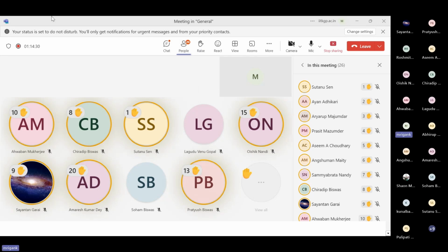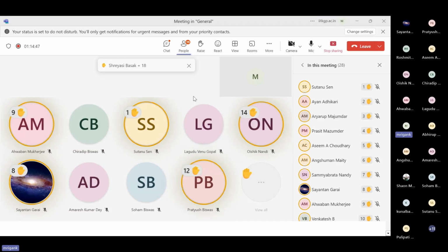So the noise chapter, the lectures on the noise analysis, is important. You should go through that, and the sizing eventually. Right now, in LT5, the problem is that the noise model we have seen is not very correct. It doesn't work properly. That's why I did not emphasize noise, because unless you can simulate it and make use of it, what is the point? When we go to Cadence, there the noise analysis will be accurate, and there we can do the sizing for mitigating noise. But conceptually, in those lectures that were recommended earlier, the noise analysis is given, and it is shown how the device sizes, input device size, load device size, bias current, all those things affect the noise of the amplifier.